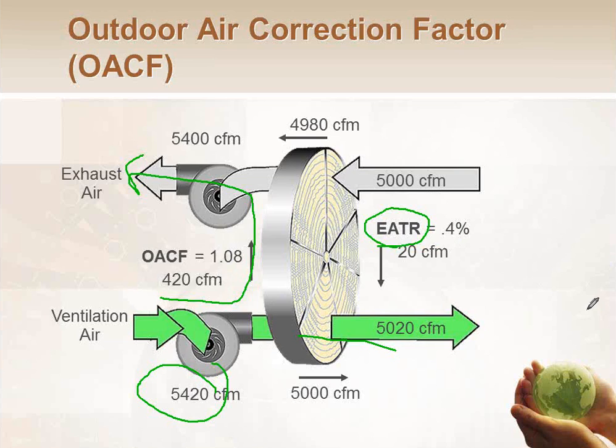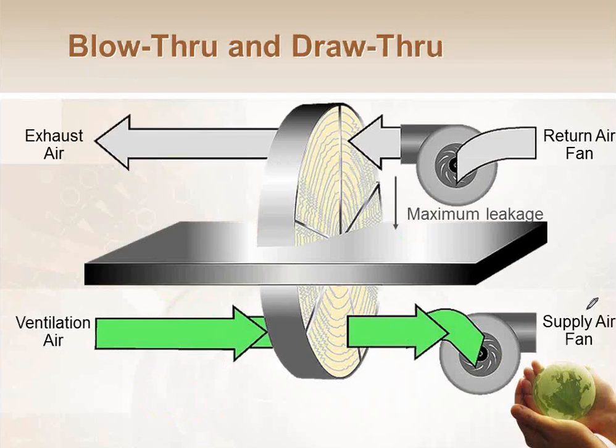Let's see. Syed asks, could the leakage be eliminated or minimized by pressurization? Absolutely, Syed, and you're leading me right into the next set of slides here. Where I choose to position the fans relative to the heat exchanger, the ERV wheel in this case, has a big difference on how much leakage I'm going to have.